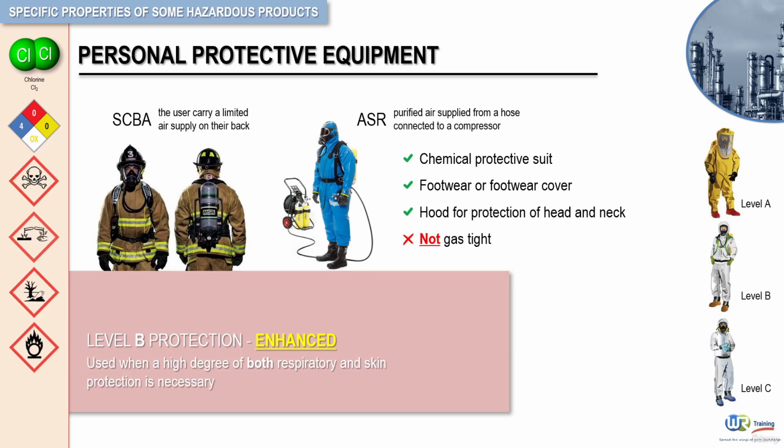For this reason, air monitoring plays a critical role in the chlorine response. Continued environmental monitoring for the duration of the response provides valuable information which will allow the responders to reduce the level of protective equipment they utilize during the response, and also assists in determining when individuals that might have been displaced by the incident can return.